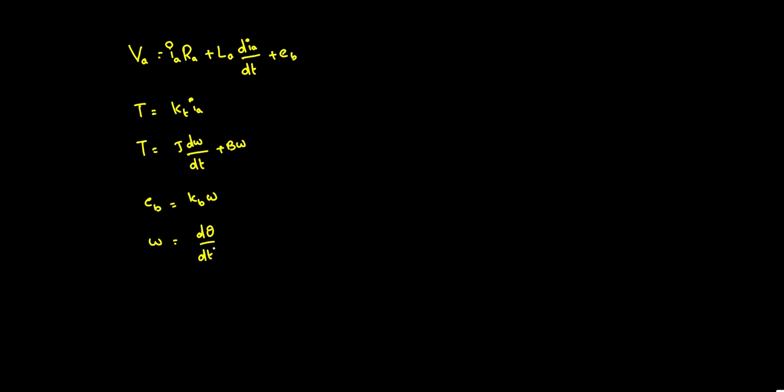Taking the Laplace transform, VA of s is equal to IA of s into RA plus LA s into IA of s plus EB of s. Let me rearrange the equation.